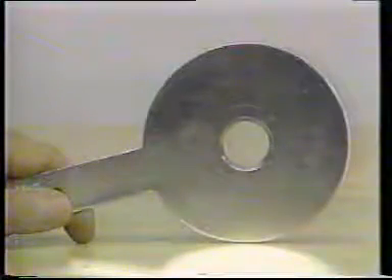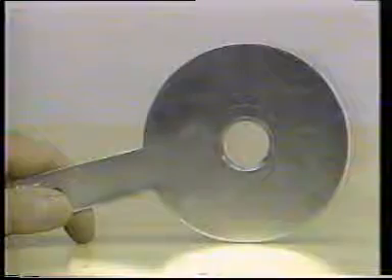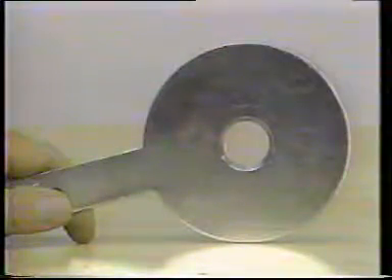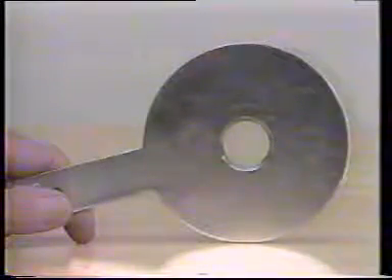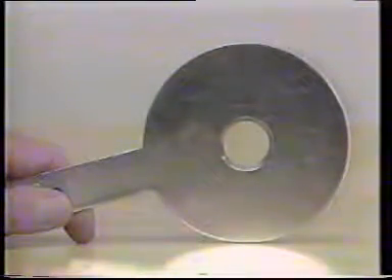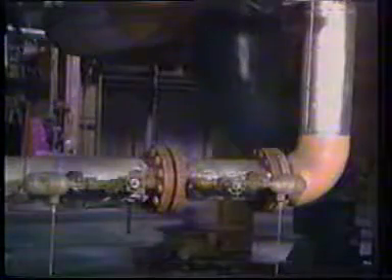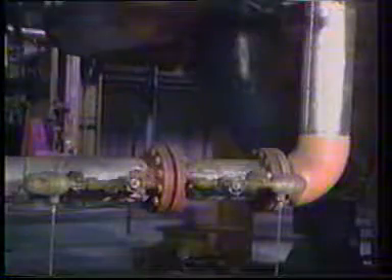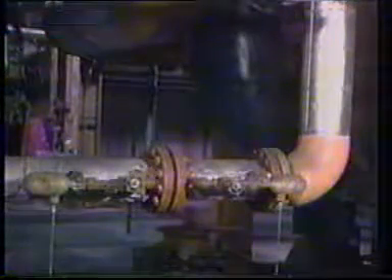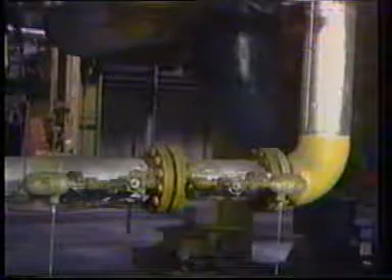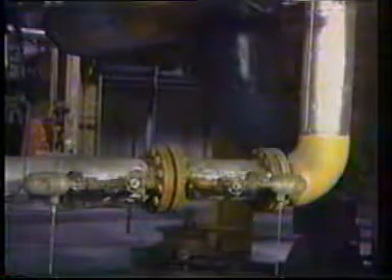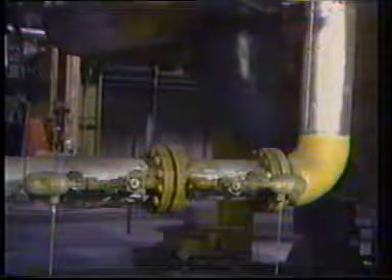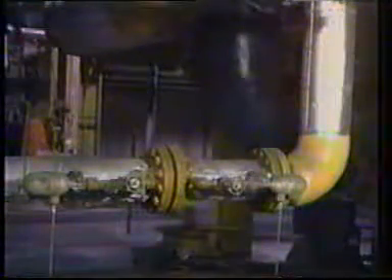Orifice plates require very little maintenance since they have no moving parts. Orifice plates perform best with clean, relatively homogeneous fluids and may not be suited for measuring high viscosity flows. It's important to keep in mind that bore wear will eventually affect measurement accuracy and require replacement of the orifice plate. In addition, weep holes and pressure taps may become clogged, causing inaccurate measurements. When clogging occurs, the orifice plate and pressure taps will have to be removed and cleaned.